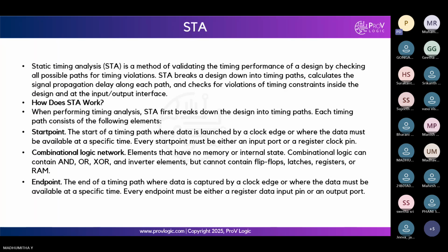If our design is going to work in 1 nanosecond, we have to make sure that all the timing paths in our design are going to use 1 nanosecond to transfer the data. To ensure this, we will be doing this check called static timing analysis.